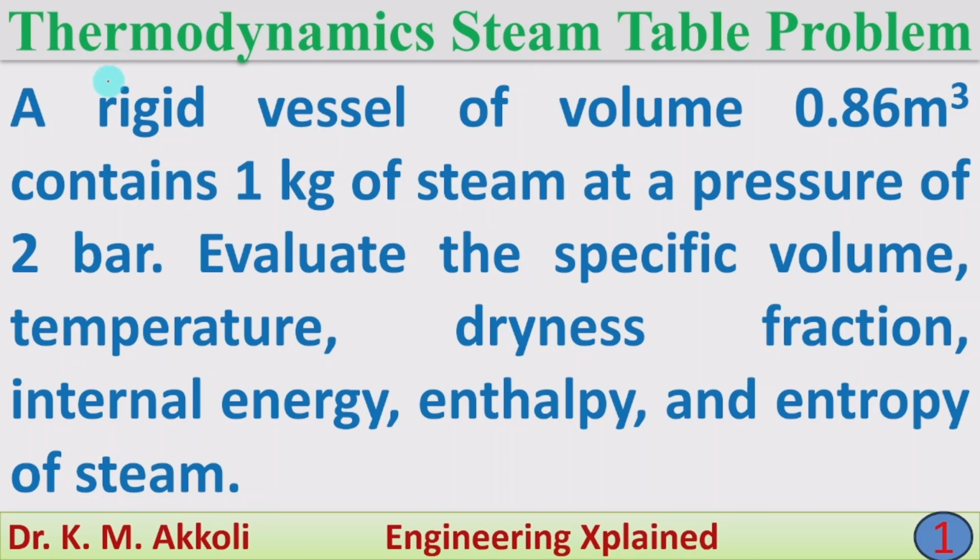In this session, I am going to solve one thermodynamics problem on the steam table. The problem is that a rigid vessel of volume 0.86 meter cube contains 1 kg of steam at a pressure of 2 bar. Evaluate the specific volume, temperature, dryness fraction, internal energy, enthalpy and entropy of the steam.